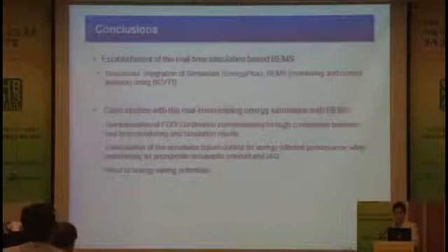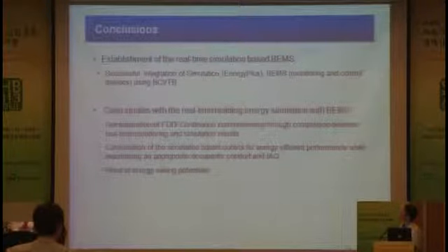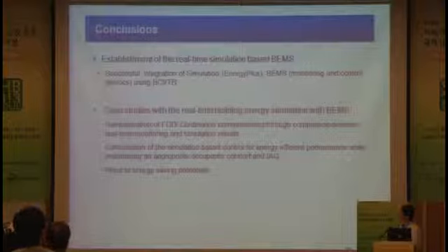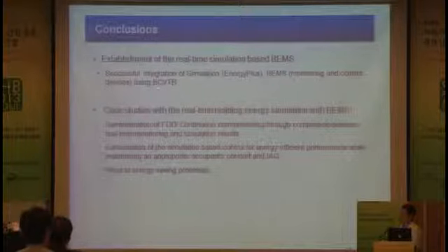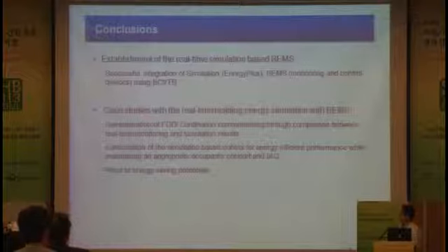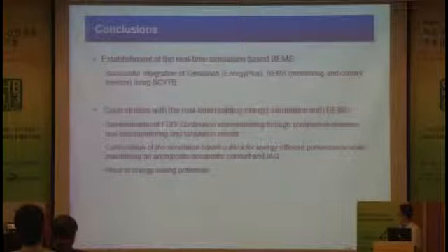Okay, conclusions. We established the real-time simulation-based BAMS system. We successfully integrated EnergyPlus and the actual BAMS system through BCVTB. Through the case studies, we demonstrated FDD and continuous commissioning through comparison between real-time monitoring and simulation results.